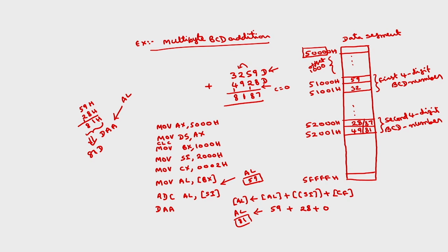Okay. Then we have to decrement CX until CX is zero; here it is only 2 bytes. If I want 4 bytes, you just simply load this with 4. Okay. So this can be extended to any number of bytes. So the next instruction, you have to decrement CX, but if I use the LOOP instruction, the CX decrement is inherently present. Because the second byte is pointed at 1001 and 2001, before writing the loop instruction I have to store the result also.